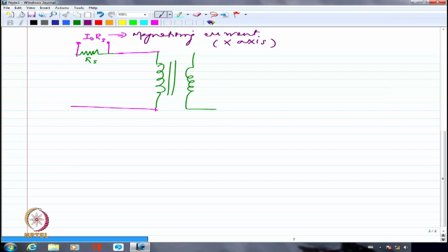So to actually give the flux value directly, rather than that, I can say normally d phi by dt is voltage. This we know, N times d phi by dt. Maybe, let me write that like that. So I can indirectly say if I want flux, I should be able to integrate the voltage. If I integrate the voltage, I should be able to get whatever is my flux. So instead of getting the voltage integrated, what I am going to do is to connect first of all a resistance and put a capacitor here.